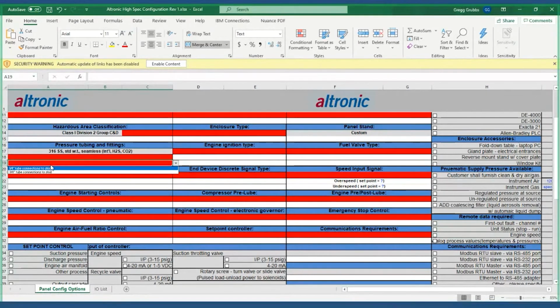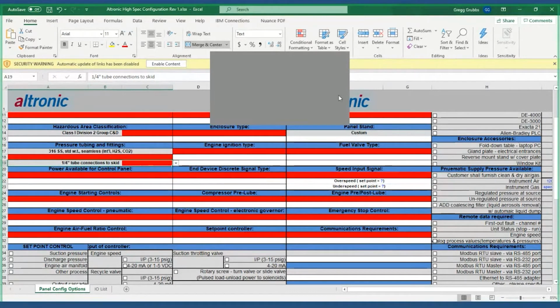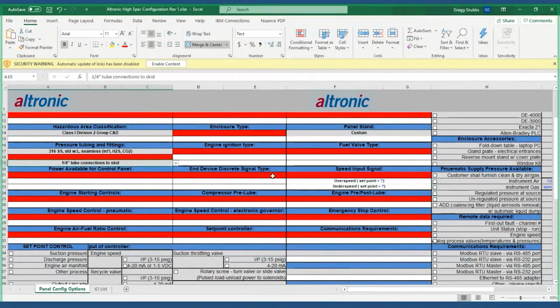You want a 1/4 inch tubing and 3/8 tubing. That's a huge deal. That's a difference of price in going from a 1/4 inch bulkhead to 3/8 bulkhead. A lot of our packagers use 3/8 to keep off freeze-offs. Further north you go, that's an important thing. So just click all those boxes. If for some reason you don't know what that is, I'd rather you leave it blank than put the wrong thing on there. So just know that we need as accurate as much of information as possible. If for some reason you need to go through these choices with me, definitely do that.